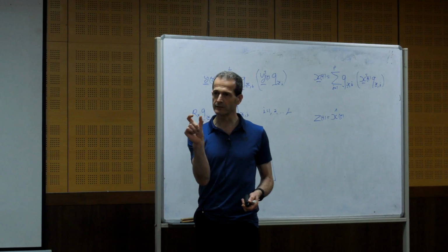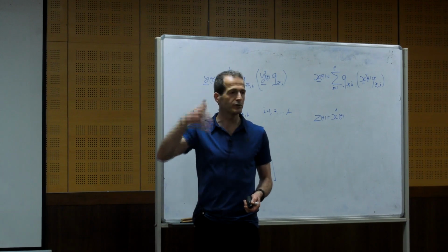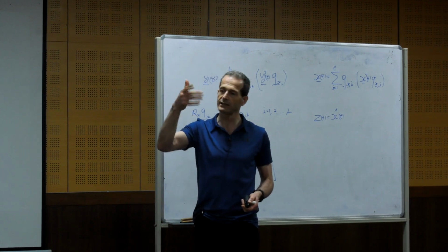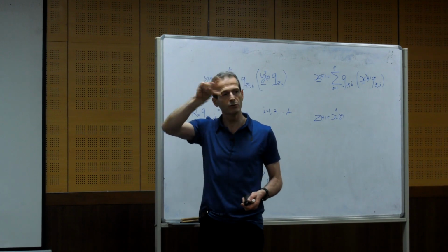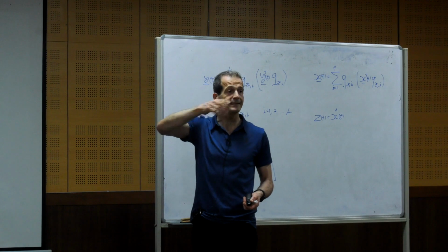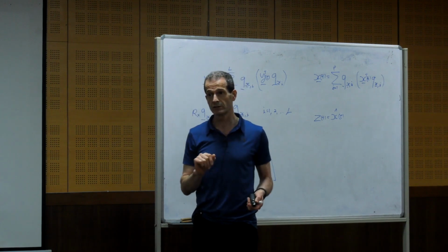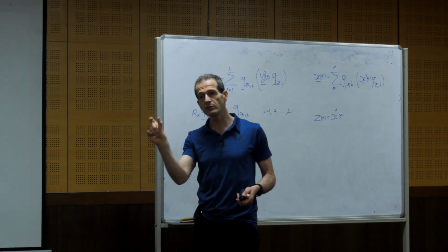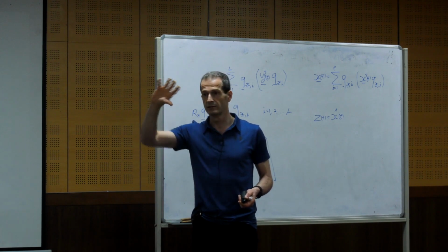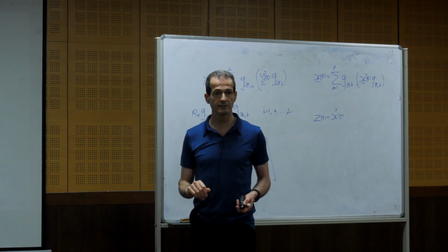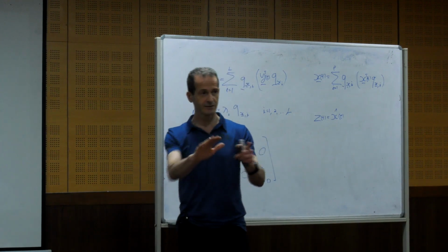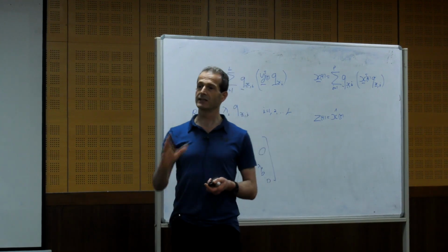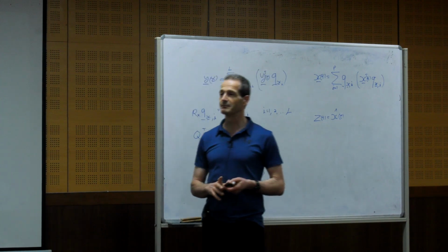And in that part, it doesn't span all frequencies. So you can see that the speech signal is contained in some of the frequencies, so we can remove noise in other frequencies without any distortion. And then for each window, we can remove noise from other frequencies. This is one thing. So it's a very good answer, by windowing.